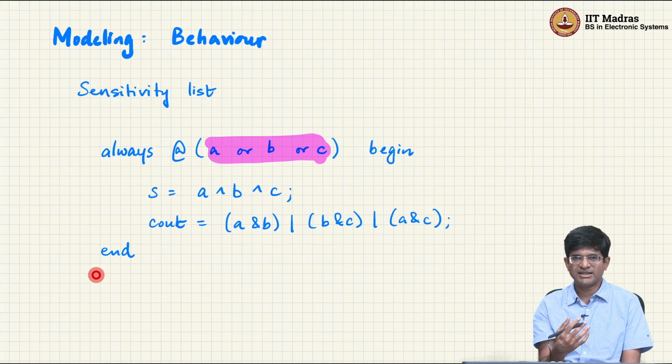That functionality is basically saying I can think in terms of registers, which is the present state of the counter, and how they sort of transfer from one place to another. I have a computation being performed based on the output of the register, either count up or count down or hold the last value or load a new value, and that gets transferred back into the counter, right? So that's a register transfer.